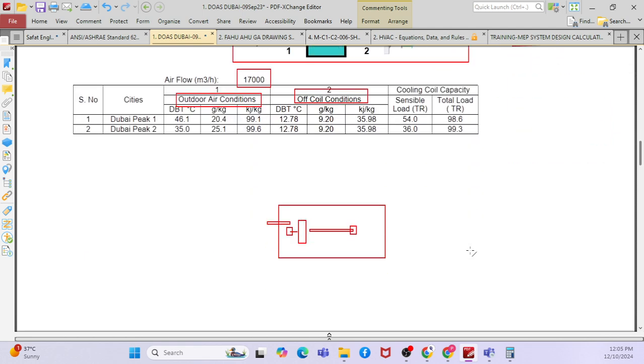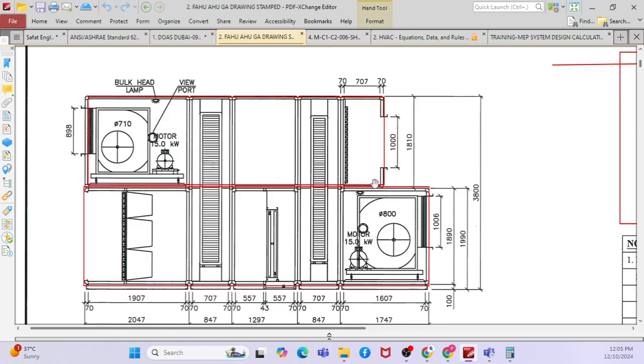If you go to this picture, you can see this type of FAHU. You can take the return from here. This return will transfer the energy only, not the airflow. The airflow will not mix, it only transfers the energy. This one has a heat recovery wheel. When the return air comes from inside, it will transfer the energy to the outside air. I can show you one picture for you to understand.